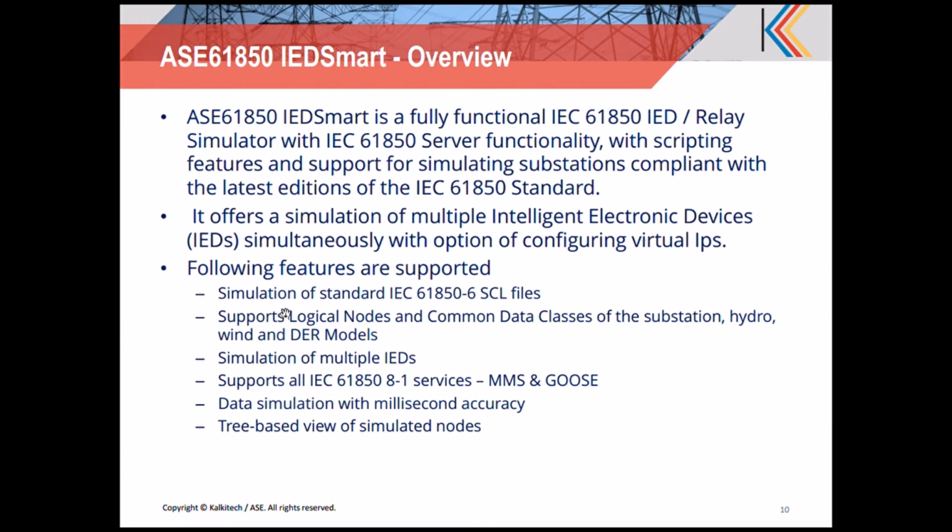Some of the features supported are simulation of all the standard SCL files as per 61850-6. It supports logical nodes and common data classes of substation, hydro, wind and DER. Simulation of multiple IEDs is supported altogether. It supports all 8-1 services, MMS based reporting, logging, and all the functionalities, plus GOOSE is also supported. Data simulation with millisecond accuracy is available. A tree based view of the simulated nodes is available, using which you can debug the steps.